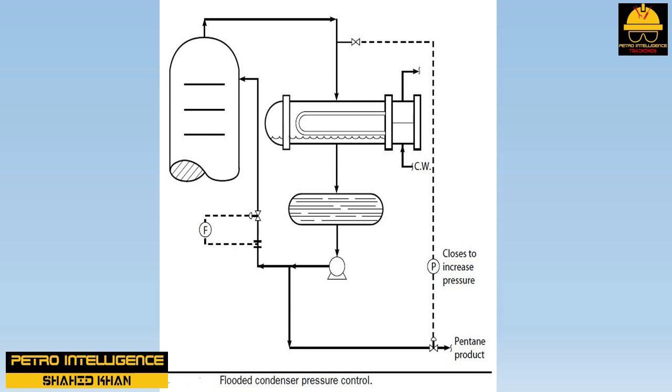The liquid on the tray deck was at its bubble, or boiling, point. A sudden decrease in the tower pressure caused the liquid to boil violently. The resulting surge in vapor flow promoted jet entrainment, or flooding. Alternately, the vapor flowing between trays is at its dew point. A sudden increase in tower pressure can cause a rapid condensation of this vapor and a loss in vapor velocity through the tray deck holes. The resulting loss in vapor flow can cause the tray decks to dump.